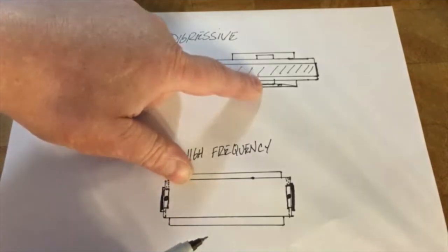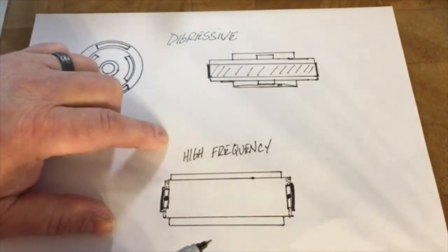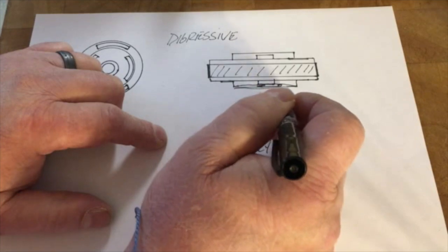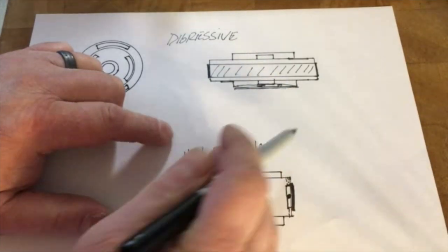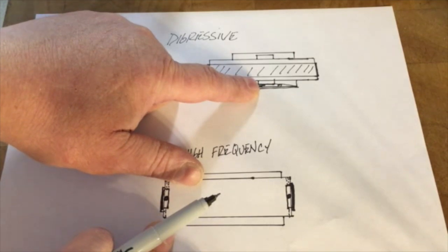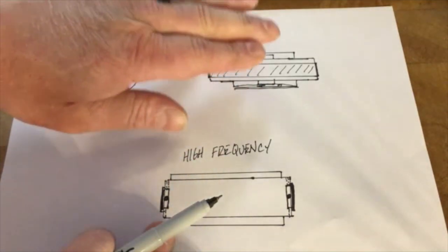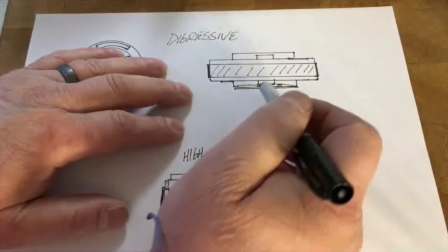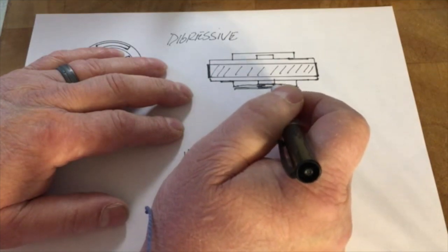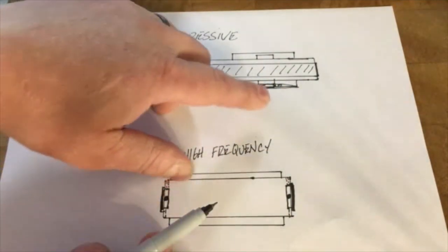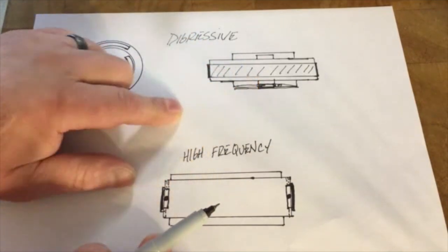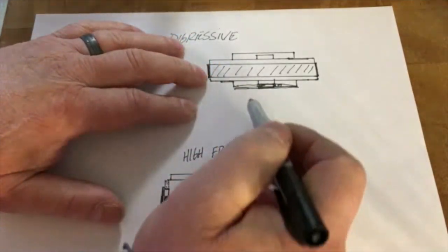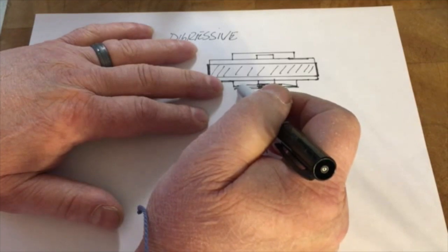But now this isn't a tuning tool. This is an adjustment. So you could take shims, put them in here so there would be no preload, they call it, on the cover plate, or you can have a lot of preload on the cover plate. So what happens if you didn't put any bleed shim in there, and you put a shim underneath here to take almost all of the preload out of that cover plate, and so you'd still have maybe a little bit of preload just to give it some tension, but with no bleed and a thin shim,